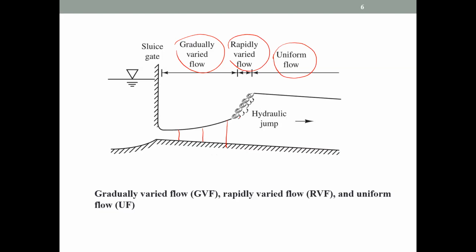The point is that you need to understand what is the cross-section of your channel that you are going to design. And when you design the cross-section, if this height cannot properly account for this kind of variation, then what will happen? The water will start overflowing, right? So this is what normally happens. So you should be able to understand the water level variation in different states. If it is a gradually varied flow, how does the water level change?